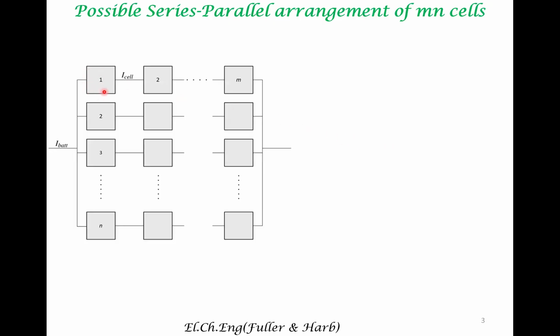This refers to a particular cell which has its own voltage versus current characteristic. Many cells are put together in series. Why do we need to put together cells in series? Because the voltages add up. While we do that, the resistance also adds up. So just from simple notions of parallel and series resistance, we can compute the overall resistance of a battery pack.